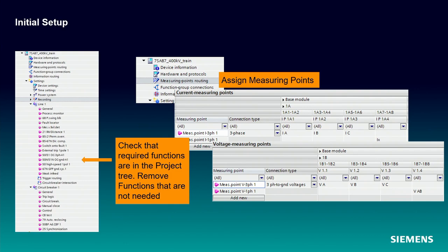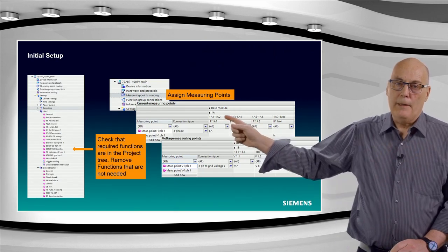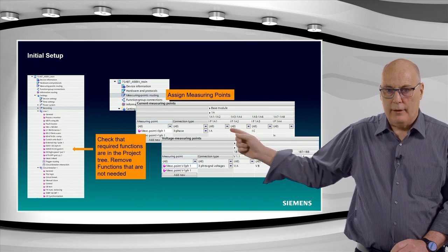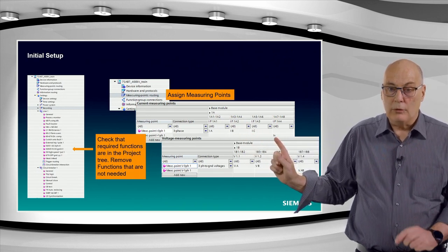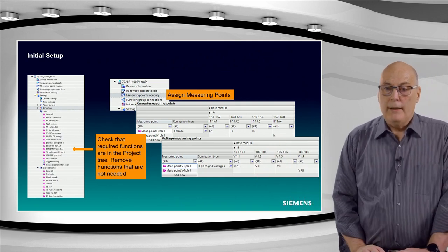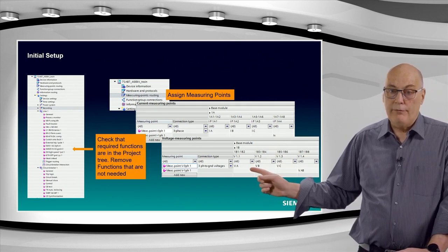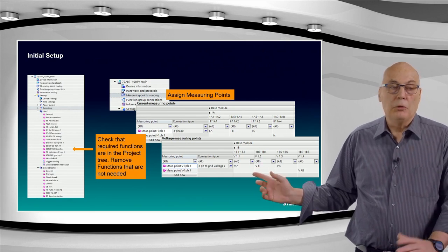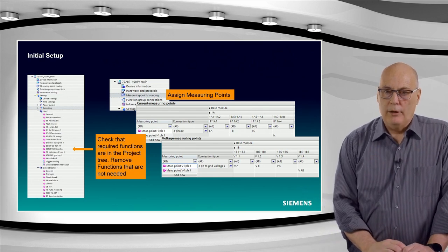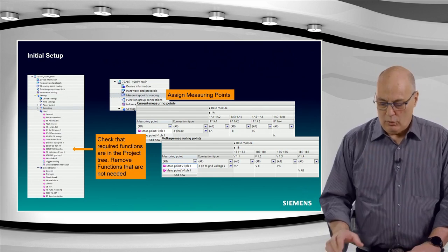Also important, if you have to really work with a relay on site, you don't need to refer to any manuals or pamphlets to find the terminal numbers. In DIGSI, you can see the terminal number of the device at the top here. There is the actual physical terminal, and the IA phase current is connected there and so on. The parallel line residual current, as we'll see later on, is connected to this terminal here. At the bottom, the voltage in a similar manner. There is also a three-phase measurement for the line and a single-phase measurement, probably for sync check, maybe a busbar voltage for sync check. Not a subject we'll cover today, but I just showed it there for completeness.